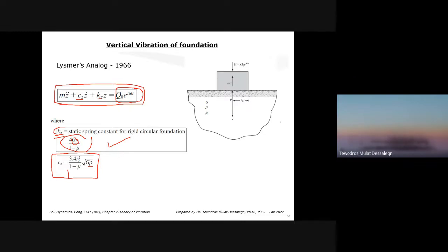So for your foundation block, actually when you design your foundation block, you can use these equations. And you can see where you are in terms of the resonant frequency. Are you away or are you close? So you can play with the G, which is the soil properties, and the density of the soil.